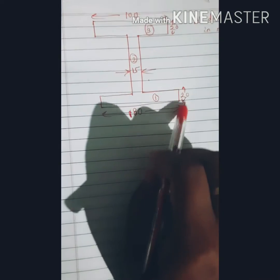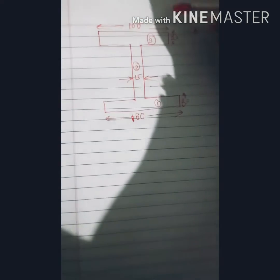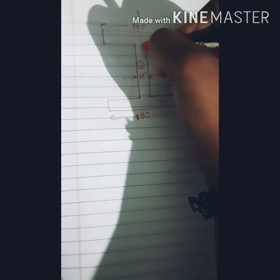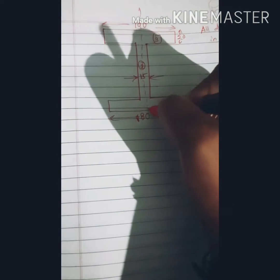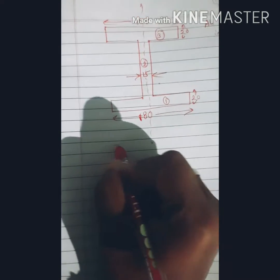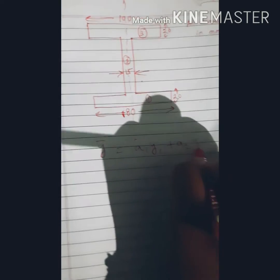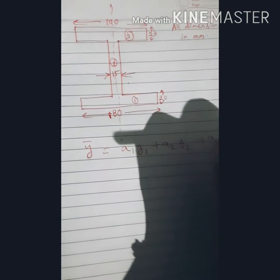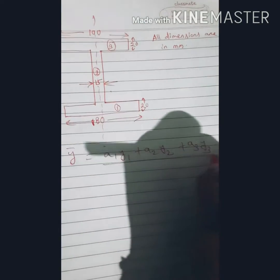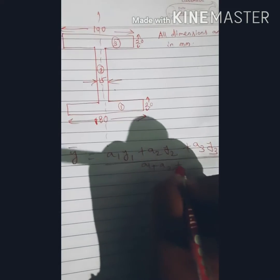For the first section, we'll take the bottom surface as a reference. Here we know that the I section is symmetric about the y-axis, so its center of gravity will lie on its y-axis. So we have to find the y coordinate. y bar equals (a1 y1 + a2 y2 + a3 y3) divided by (a1 + a2 + a3).